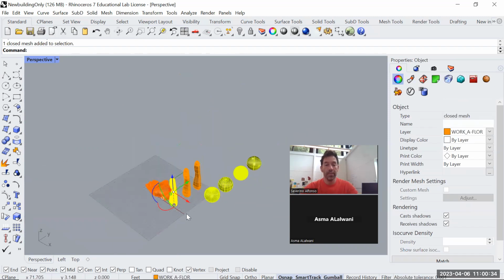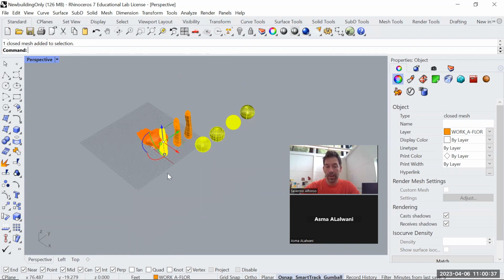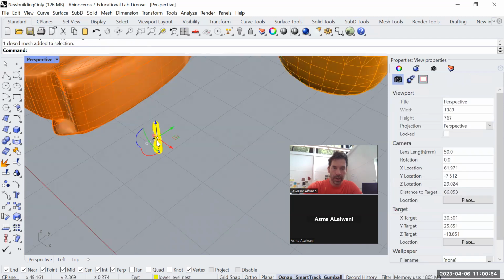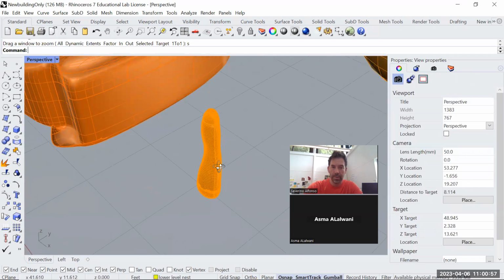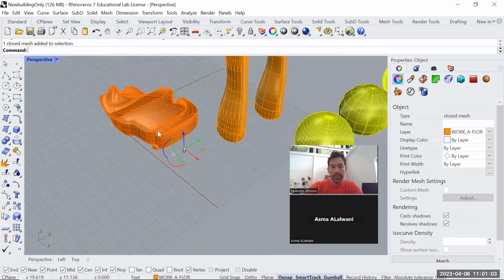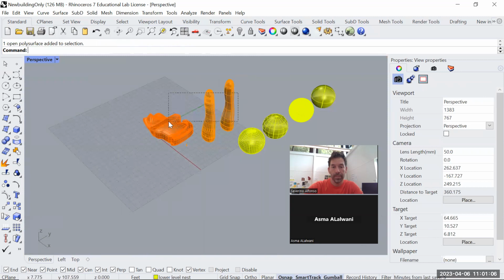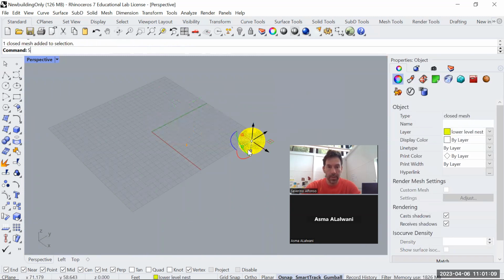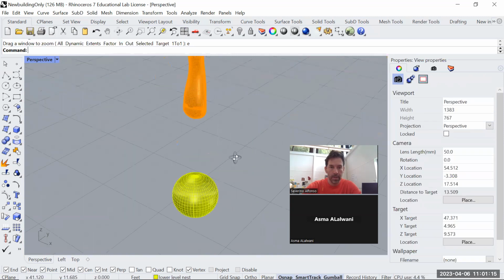Okay, so now let's think of the scale. The scale is the same. You're going to have to scale this the same way we scaled the line drawings in the laser cutting. You're going to click and say 0.00, whatever it is, and you're going to have a small element that is precisely the scale that you want. I'm just going to do it manually now, but remember that you have to calculate that number with a simple division.